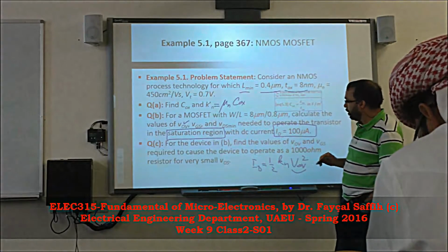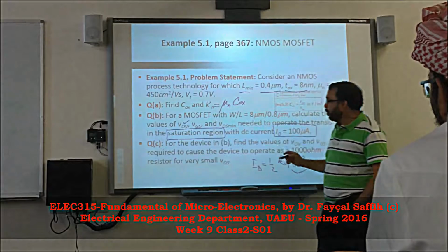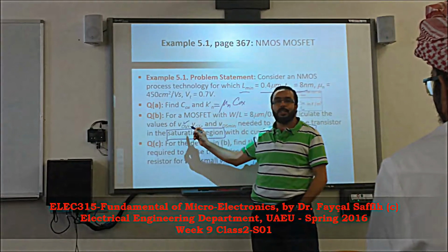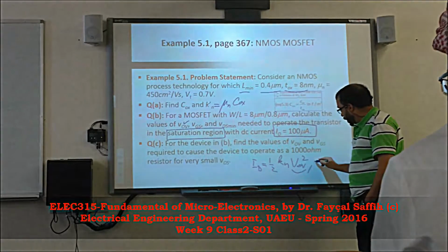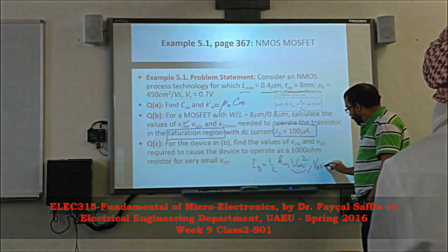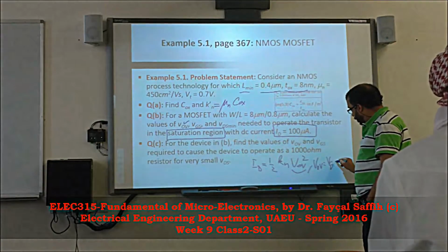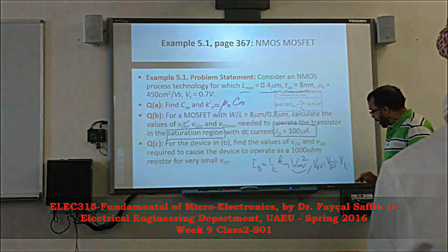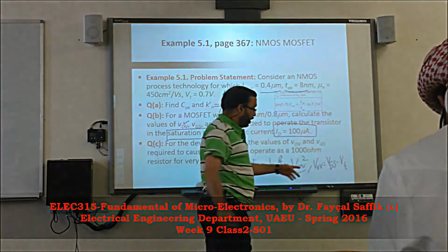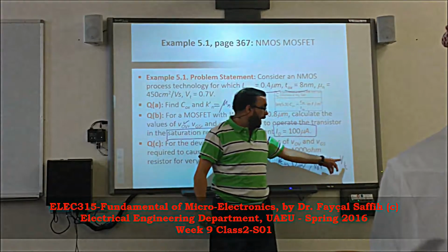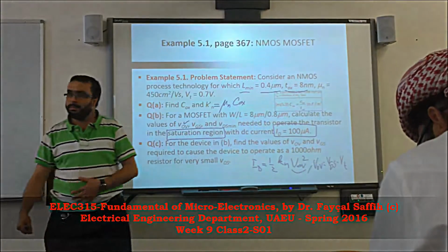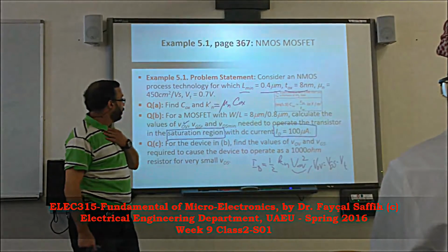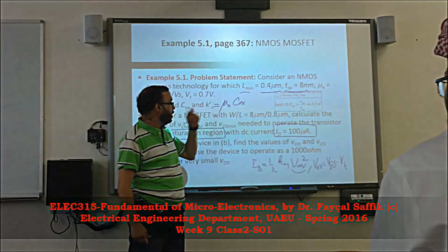Very good. So we did that. This VGS, what's the relationship between the overdrive and VGS? V overdrive equals VGS minus VT. Exactly. So here, the overdrive is actually VGS minus VT. In this case, the overdrive, we have it, yes or no? All we need to do is add VT to the overdrive to get VGS. Done. Good. Excellent.